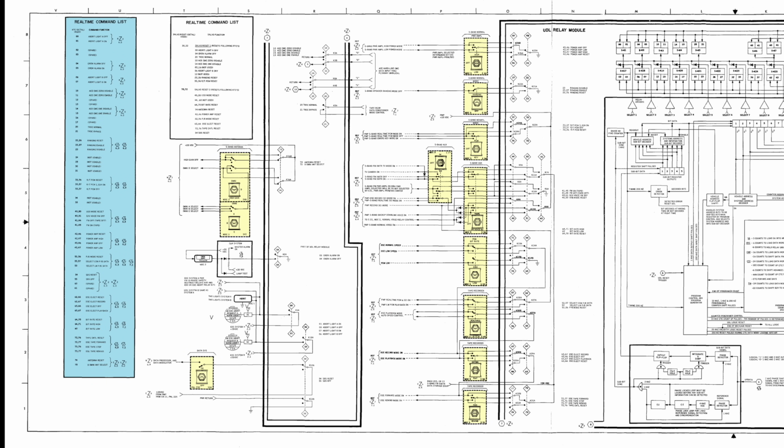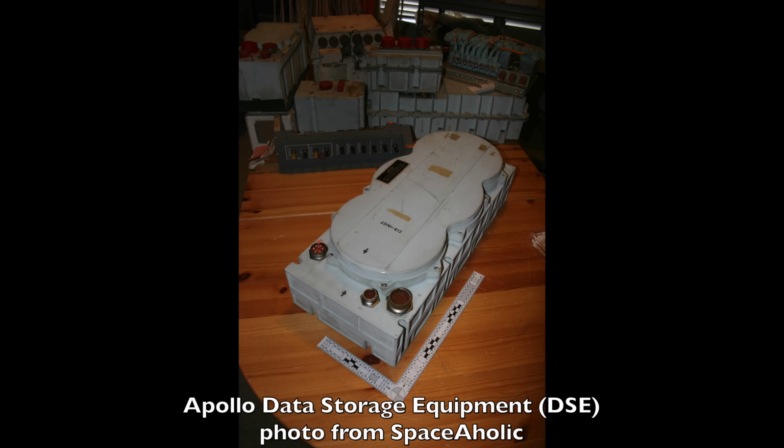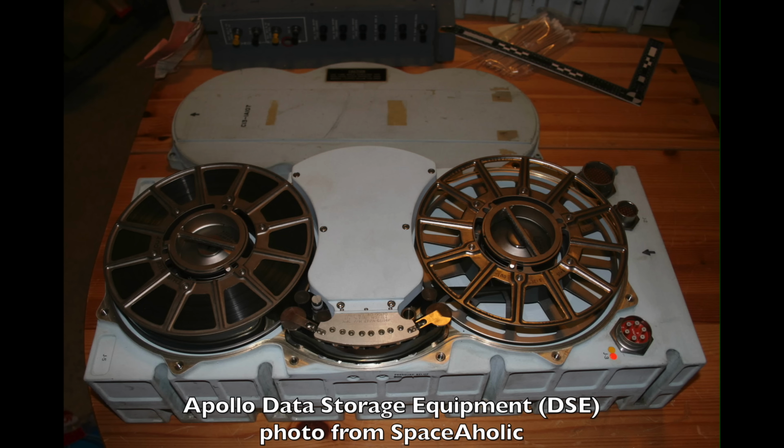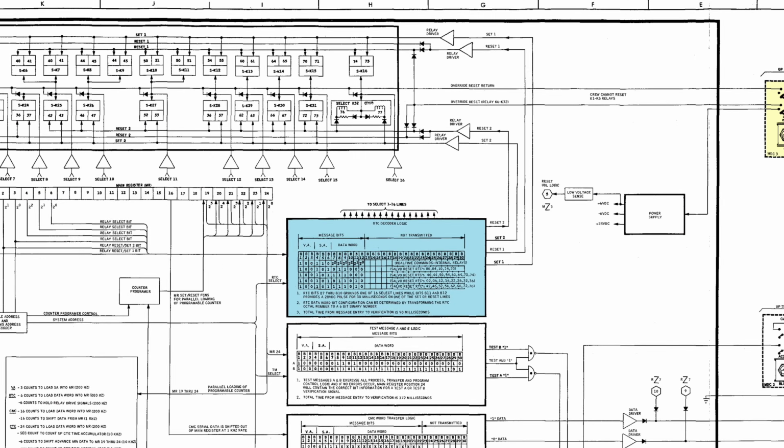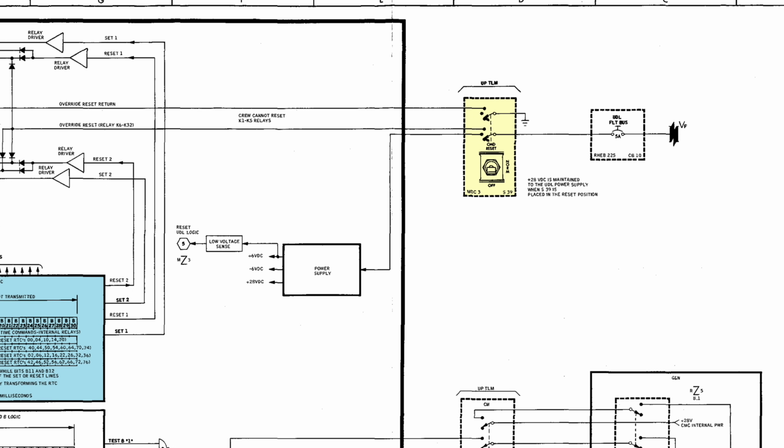In practice, the astronauts were rarely bothered with setting ranging, telemetry, and data bit rates manually, nor did they have to manage the tape recorder voice and data dumps. This was done from the ground via RTCs, lightening the workload. However, if you had to, you could flip the up telemetry switch, the same that we just flipped up to reset the relays, to the down off position instead. That would shut out the ground commands entirely, in case you were worried that the Soviet equivalent of CuriousMarc and team was tinkering with your spacecraft.